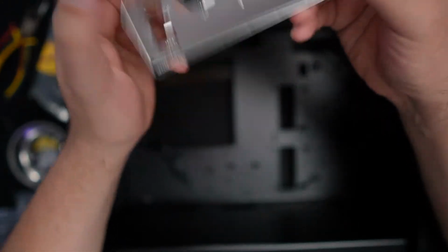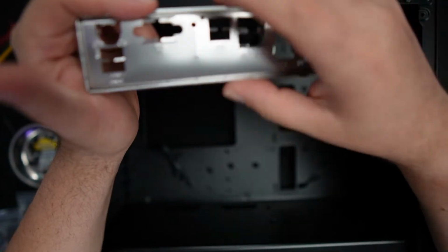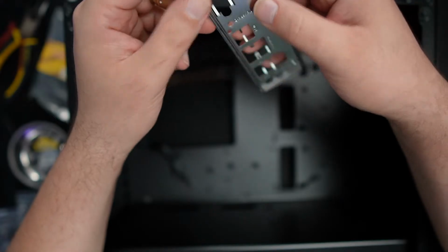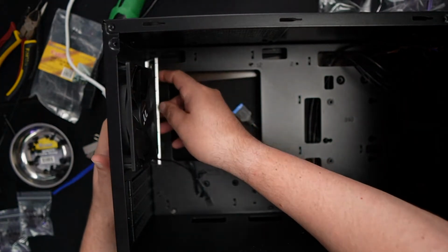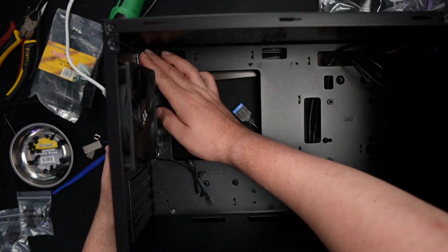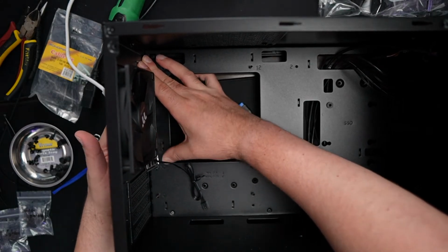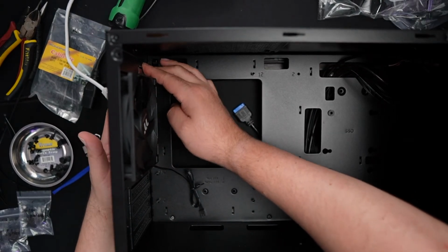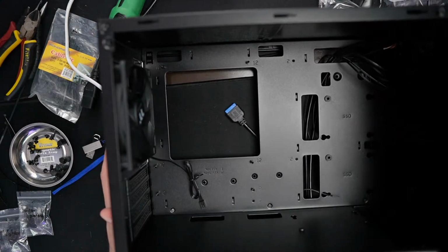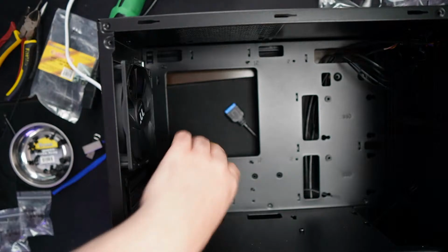If your I/O shield has any type of little metal tongues on them, just push the tongues up and out of the way. If this one doesn't, we're just going to install it. It should install to the back part of the case. It should only go one way. It should go the right way. If you have it the wrong way, flip it over. Push it in place. Just be careful because they are sharp. You don't want to cut your finger on it. That would be a really bad day. So just don't cut your finger on that.